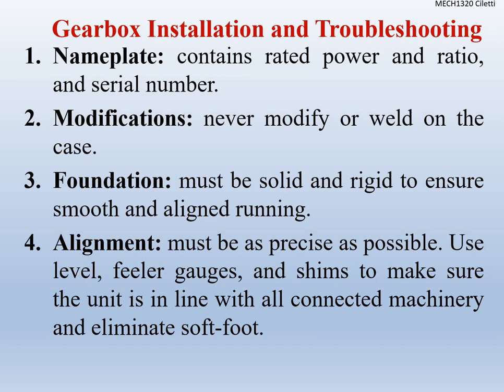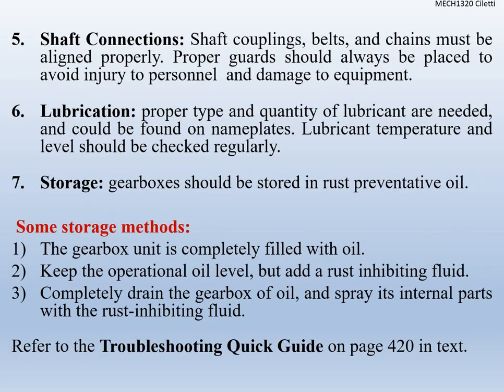The foundation has to be solid and rigid for smooth alignment, and alignment has to be as precise as possible. So use a leveler, feeler gauges, shims, all stuff that we're going to use in the lab anyways when we mount the motor. We have to make sure everything is in line and all connected to the machinery, and we eliminate a soft foot. We're going to cover that in a lab.